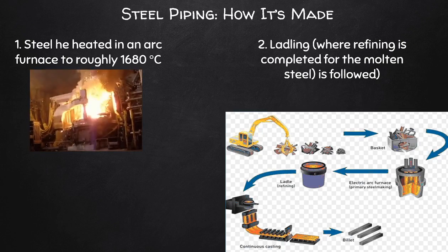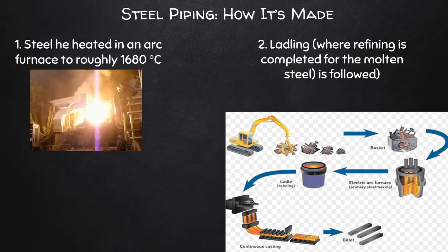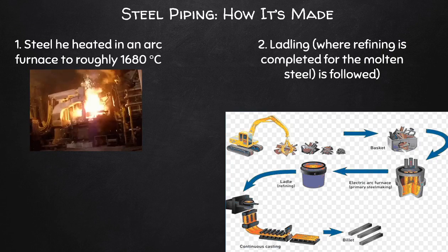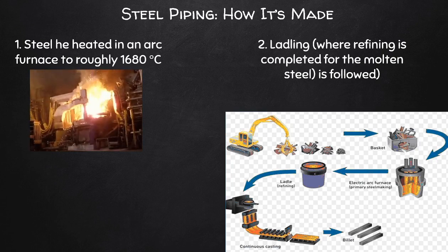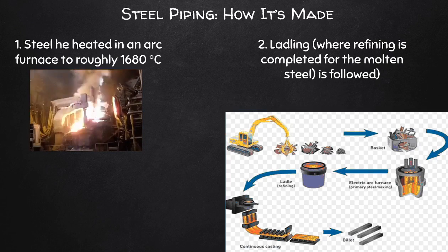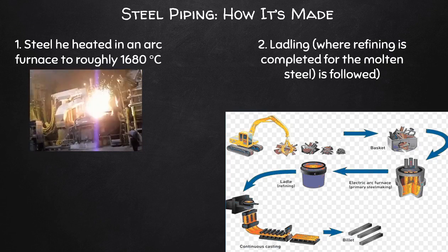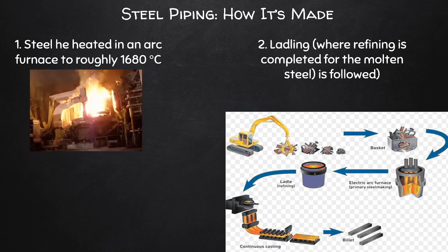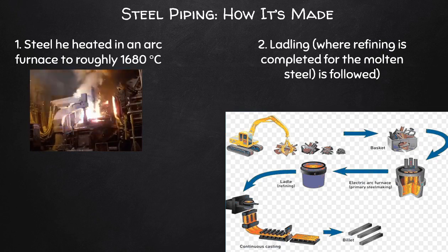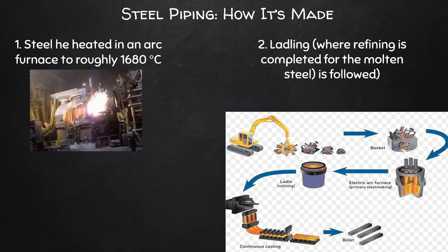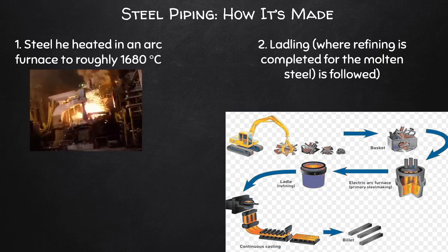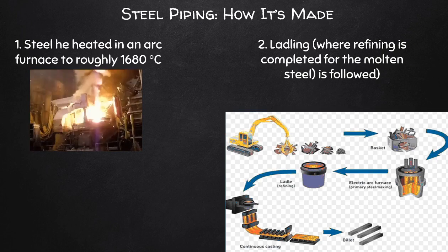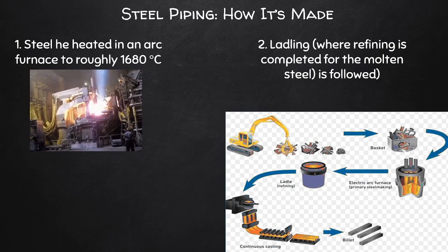All right. And then the steel is heated to very high temperatures using an arc furnace, which operates above 1000 degrees Celsius, to melt the steel before you add additives. You can usually add the additives during the ladling. Ladling is where you pour the molten steel into a ladle, a massive vessel containing maybe 60 tons of steel. These additives will then prevent oxidation and scaling, and also improve the overall physical properties of the steel that you're making, and also change the grade of steel that you're making.